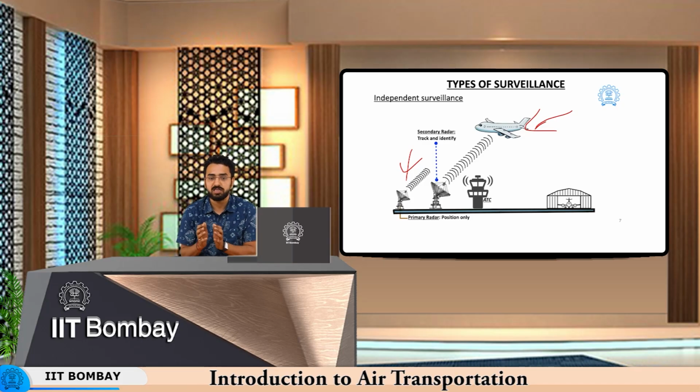Before the initiation of the flight itself, these squawk codes are provided to the particular aircraft, and subsequently these squawk codes are transmitted to all the nearby ATC towers, so that tracking of whether the aircraft is identified is possible, and hence we can understand whether the aircraft is actually a friend or a foe. This is how the secondary radar services work.